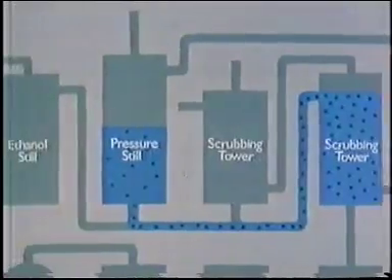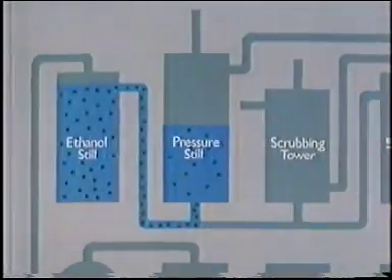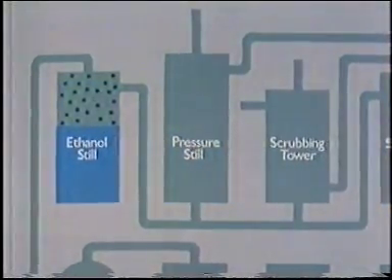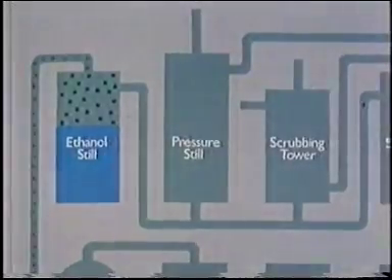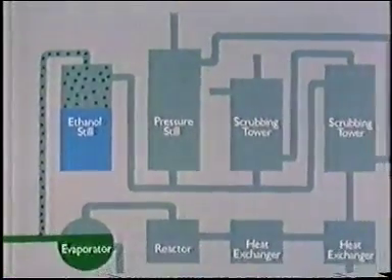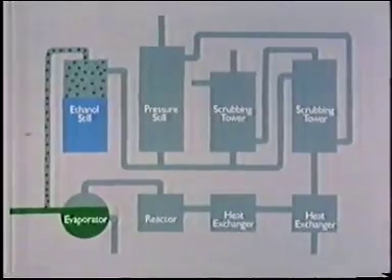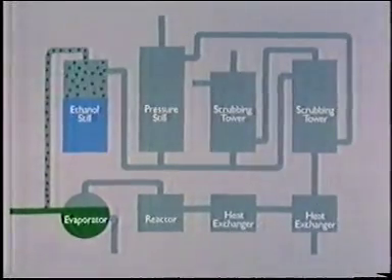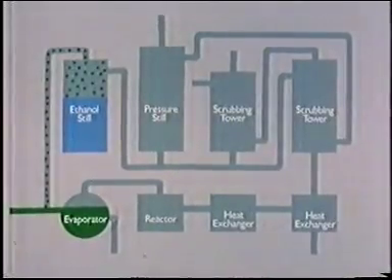The rest goes to another still where ethanol is recovered and then is recycled as vapor to the evaporator, where fresh ethanol feedstock is also added. The process is continuous and is maintained working for up to a year at a time.